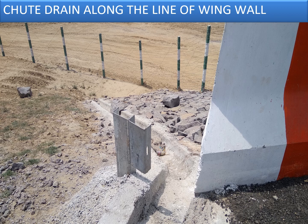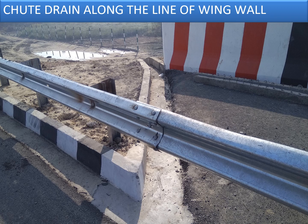So what will happen is, even if you have provided a drainage like this, it will not serve its purpose, rather it will also have an impact on the erosion of the soil under the stone pitchings. As you can see, some of the stones have already settled because of the erosion of the soil below. So it is always required to close the curb lines which are close to the structures, whether it is a PUP or a VUP, properly, and they should be directed straight as far as possible for the discharge of the water to be out of the road purview areas.